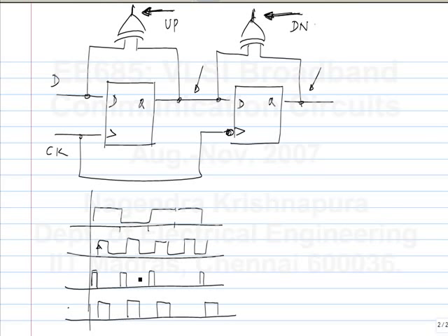So what I'm saying is the purity of the sine wave that you need in this case is not as much as the purity of the sine wave that you need to generate as a reference signal in a radio or something. You have this clock and the clock is supposed to be here. Because of all these disturbances, it will move a little bit from this. As long as it is not too much, it is okay. And how much is too much is much more in the clock recovery case than in the frequency synthesizer case. You can tolerate a lot more jitter in the clock recovery case. And there will be more jitter anyway because of the changing data pattern and so on.